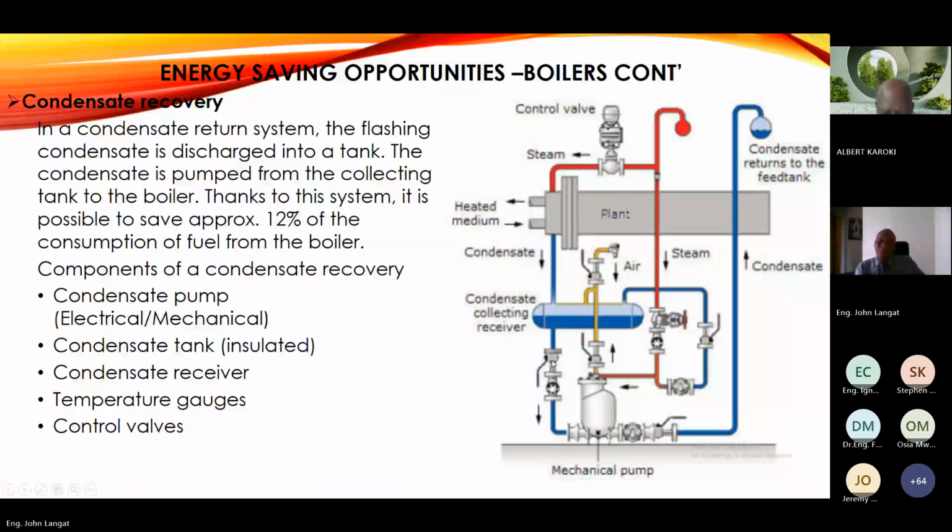This is an Ogden pump. The Ogden pump is actuated by steam at low pressure. Normally, this low pressure steam is operating at 2 bar. It uses the ball cock, which floats as a result of the condensate filling the receiver. Basically, the mode of operation is like a hydram, but a hydram is operating on cold water. So the condensate pump, which is normally called the Ogden, pumps the water into the condensate tank.